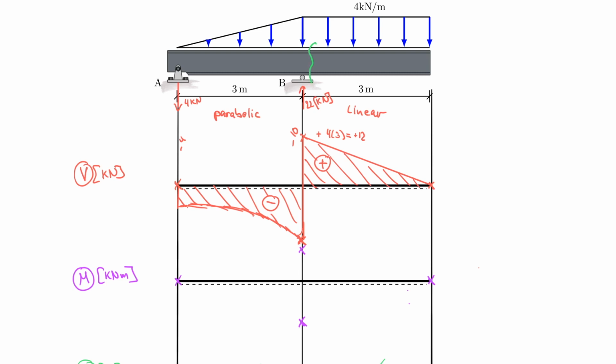So I just do it here for now, just because we want to be fast in this example and I don't have to steal more of your time. So I now look at the right cut here, at this portion, and therefore I have to put everything within that cut cloud into equilibrium with that moment. And you can see that the moment is turning clockwise and everything in this cut cloud is also turning clockwise. Therefore, this cannot be in balance unless I flip the arrow around.